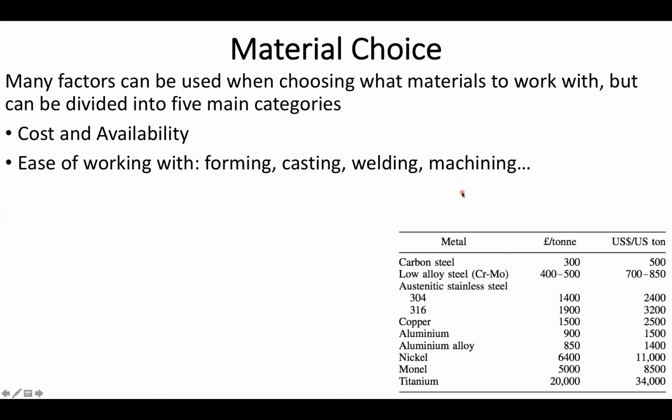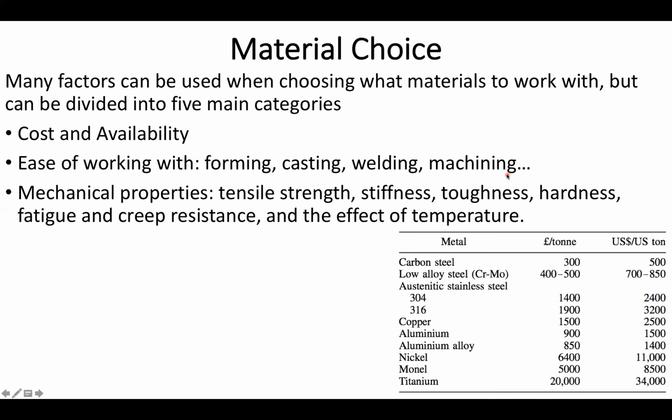You also want to be very aware of what sort of techniques you're going to need to use for the installation. It turns out that some very durable or cheap materials are not exactly that great at welding, and some can't be cast at all. So think very carefully about what sort of physical manipulation you're going to need to perform upon the material you're looking at.